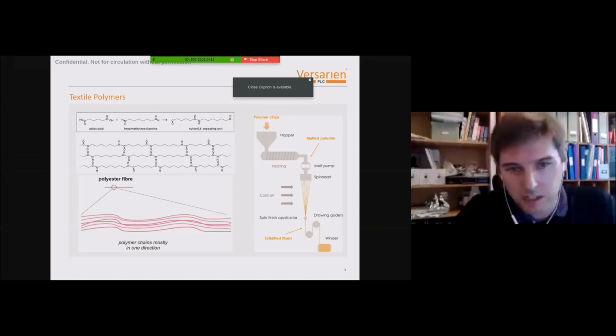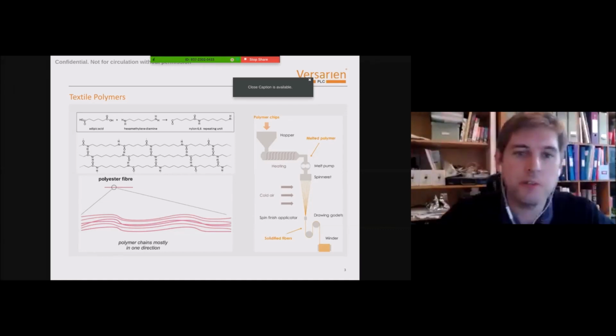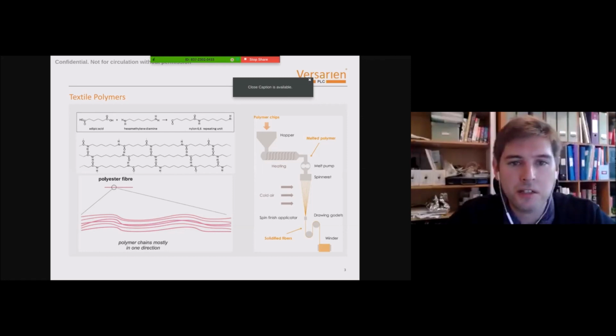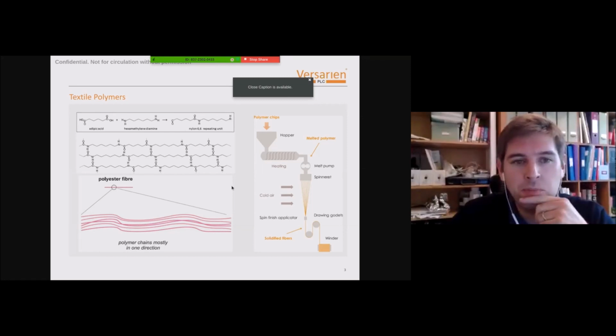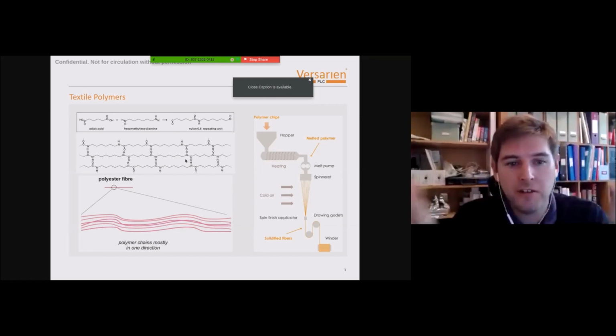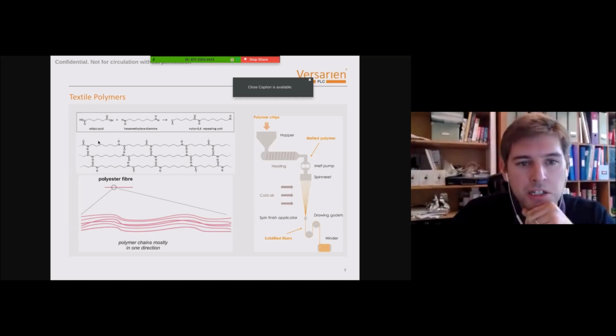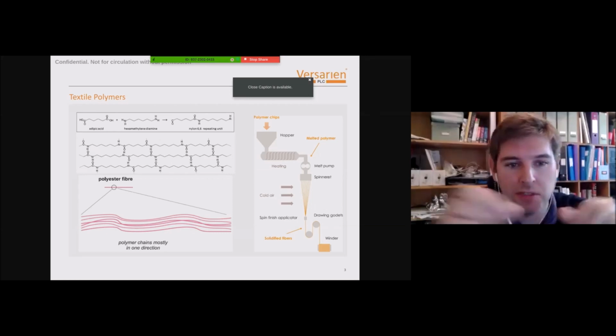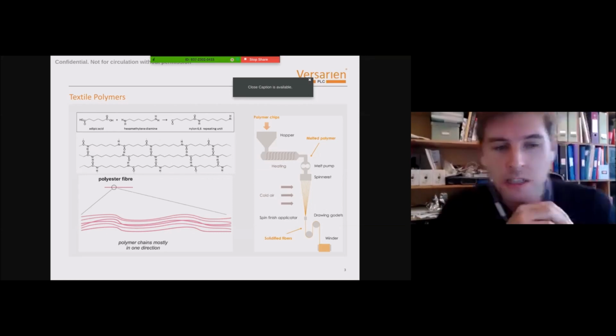just wanted to explain how similar graphene might be. So if you take something like nylon, which is called polyamide, so these are very long chain molecules. So these wiggly lines here are basically carbon atoms linked together in a long chain. And when we make a textile fiber, we are aligning these molecule chains into fibrous structures.